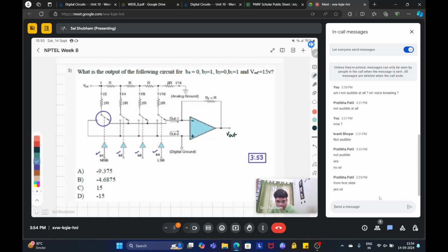The only hint I would like to give you all is that since this portion is grounded, there's a concept that since the voltage between these two are so small, we can assume that if this voltage is Vx, then this voltage is also Vx. Okay, approximately. So in this case, this is the ground, Vx equal to 0. So that means that this node is also grounded. I think this will help you to solve this question. I think this is sufficient to solve this question. The rest that you have to do is to use the network analysis.